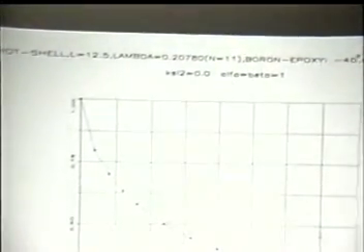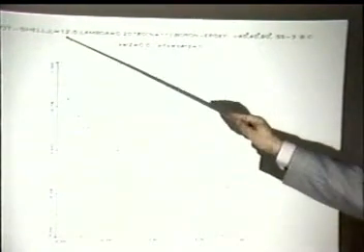Okay. Now, let us see what happens when we start looking at its different effects. This is alpha and beta set equal to 1, Xi2 is 0, so this is just the effect of having Xi1 varying from 0 to 1. And this is a type of curve that looks very much like a Koiter curve. It knocks down quite a bit, just the presence of that one imperfection.